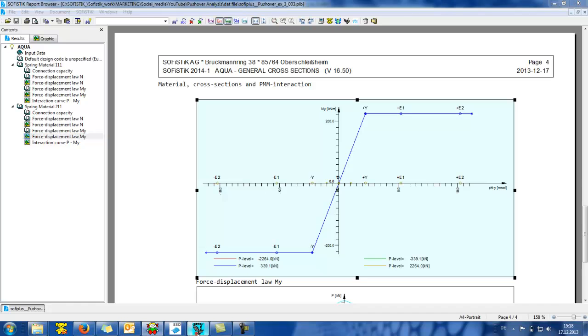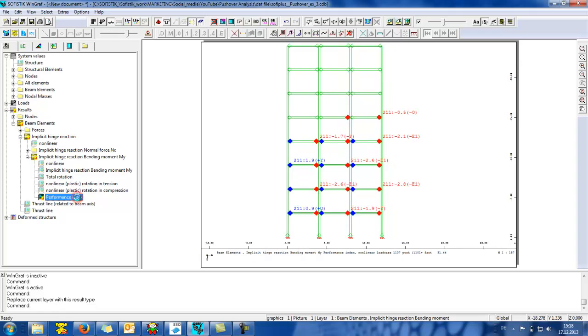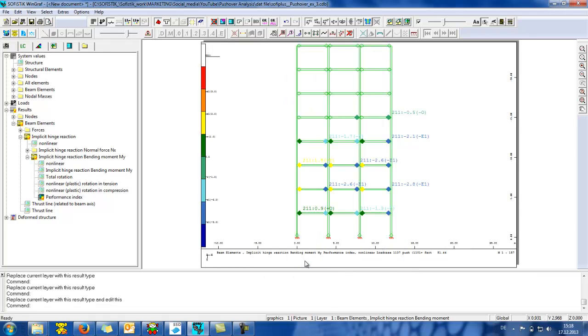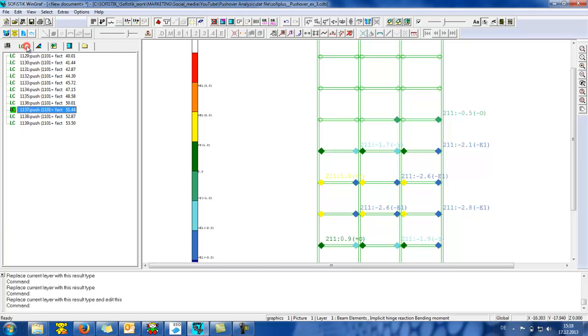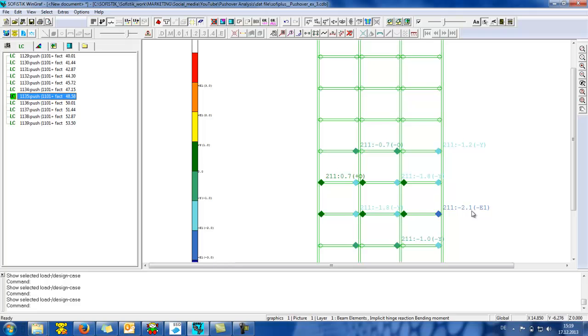So we go to WinGraph and we check the performance index graphic, and we double click and check the varying colors. At the left it is clear that we get the intervals that have been defined in the workflow. So now, very easily, we can see how the hinges perform for every load step. Also, this differentiation in the color can make the post-processing of the results even easier.